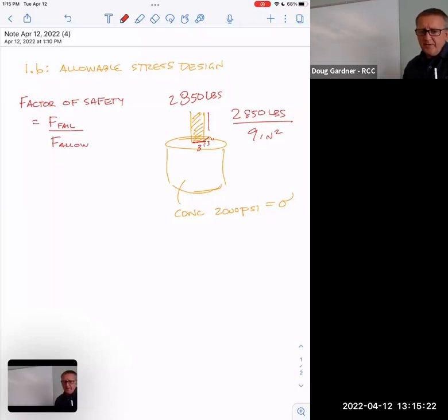So that's kind of where factor of safety comes in. It's like force of actual failure divided by the force you allow. So for instance, in this example right here, the force of failure is 2,000. And if somebody said, well, let's not go all the way, let's not allow clear up to 2,000, let's only allow up to say 1,500. So there's your force of failure by the manufacturer. It'll hold 2,000 PSI, but we don't want to push it. So we're going to put the weight limit of the bridge, if you will, at 1,500.